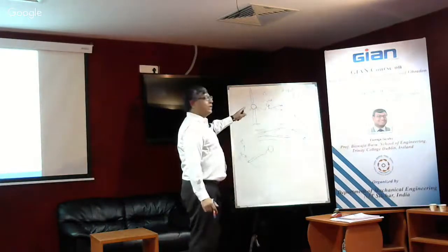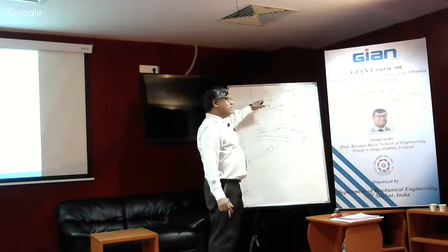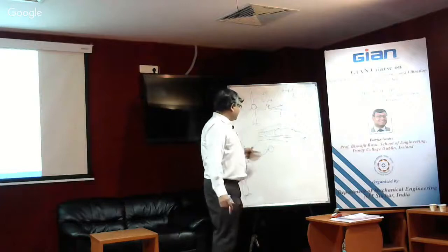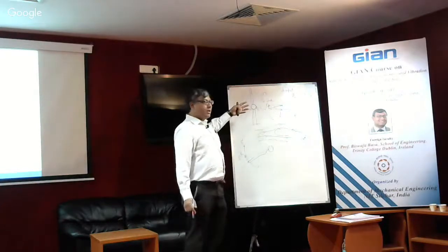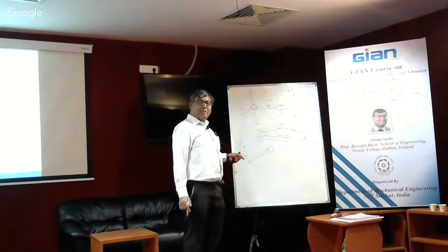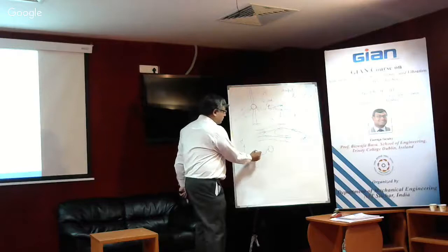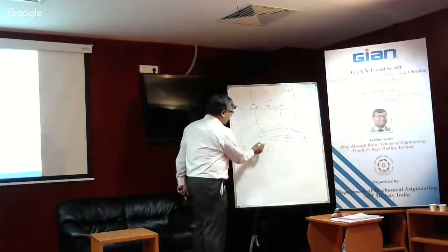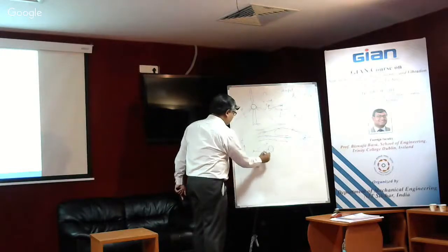So effectively, two velocities are acting here. One is omega r, the other one is the velocity of the wind. Now, the velocity of the wind is not changing, assuming it is more or less uniform over the rotor plane. What is changing is omega r. And omega r depends on the position on the blade, because if you're at a distance of r, then this is going to be omega times small r.